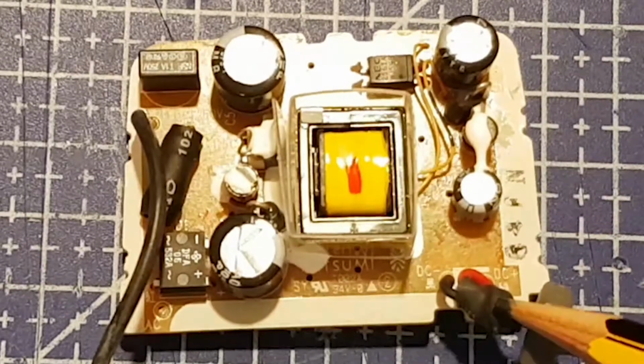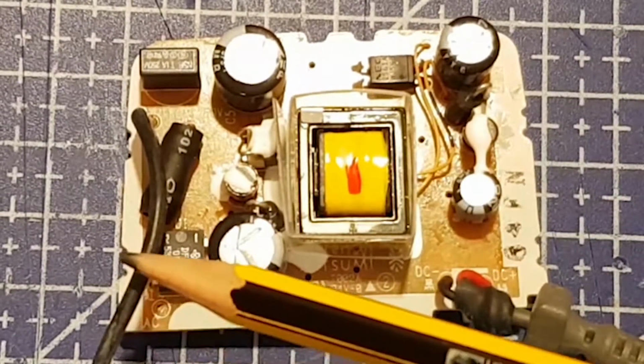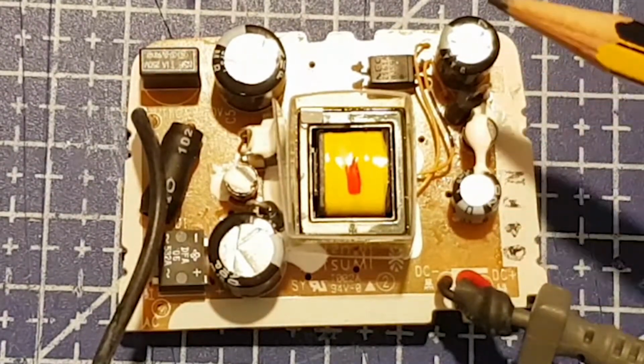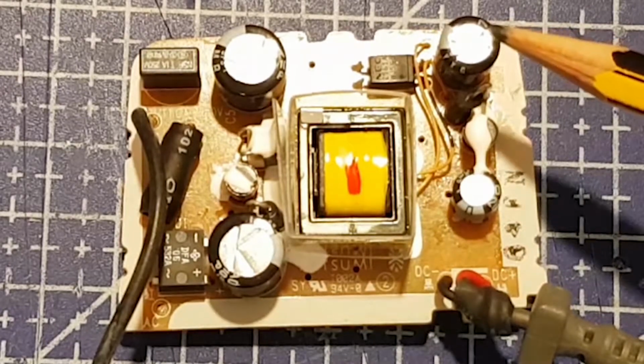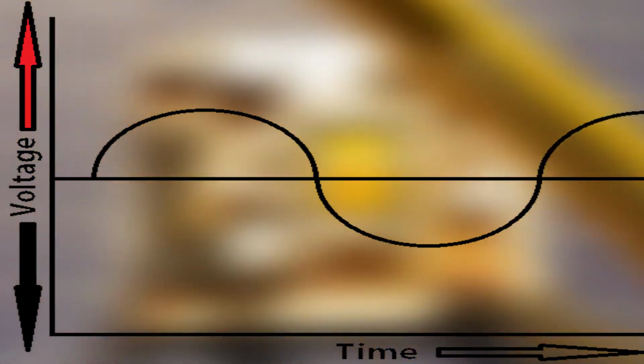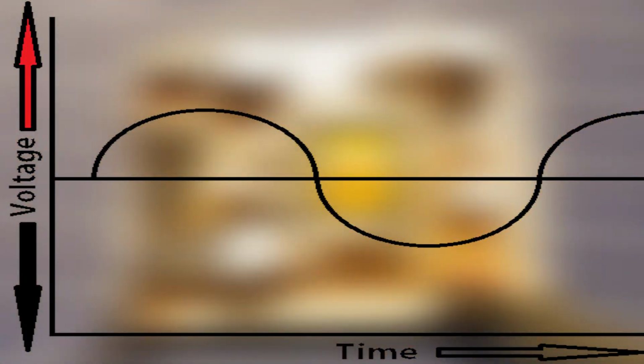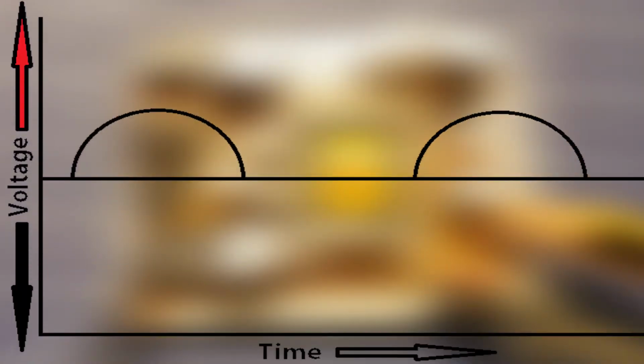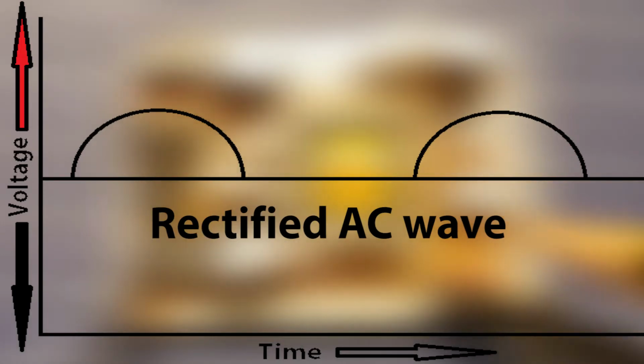Now, because we're starting off with an AC supply and we're moving over to a DC supply, we use the capacitors to filter the ripple of the output voltage. So whereas the AC voltage is going up and down, we want the DC voltage to be a smooth straight line. We use the filtering capacitors or smoothing capacitors to do this, as capacitors like to resist the change of voltage, so they smooth out the curves on an alternating current.